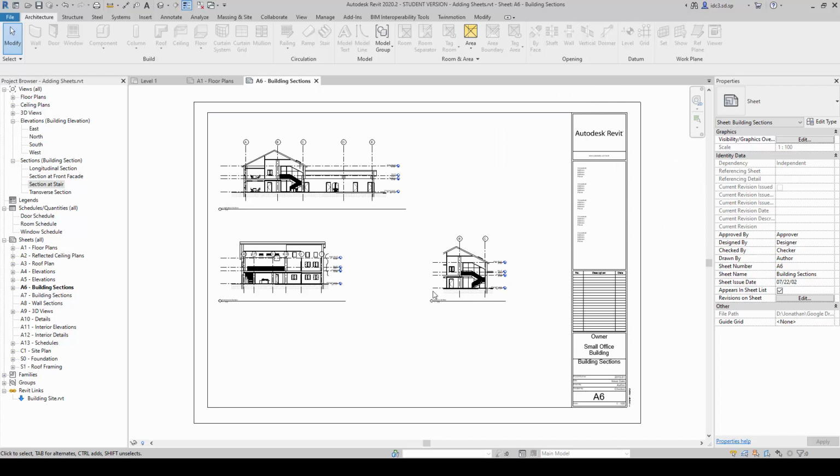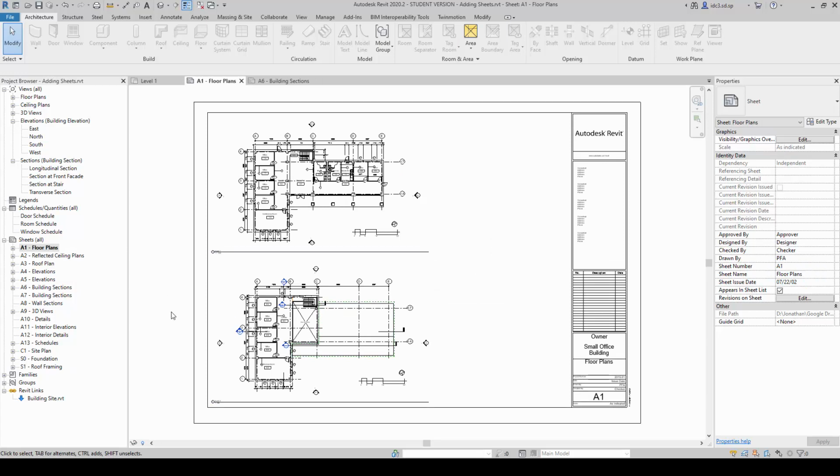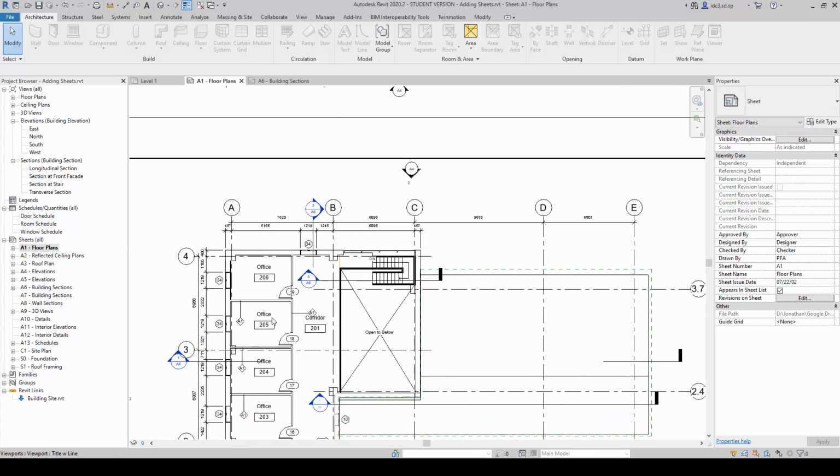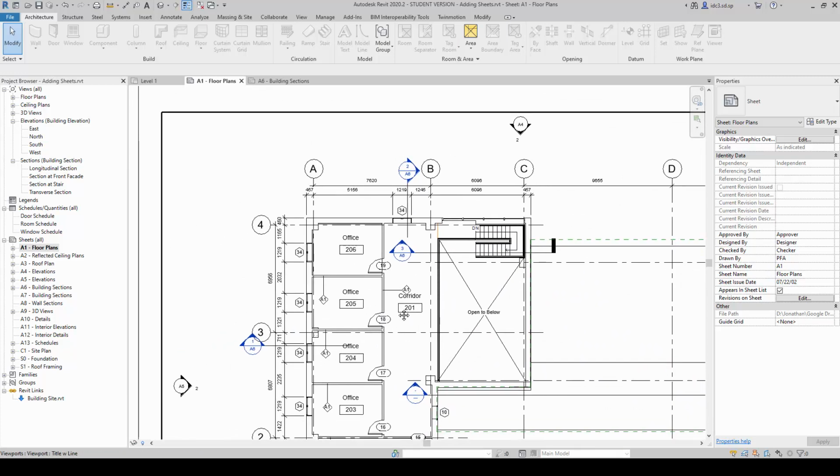And when this part is done, we will go back to our main floor plan here and zoom in to take a look. You will find that what used to be blank will now have the information of the drawing detail tag number and the drawing sheet updated.